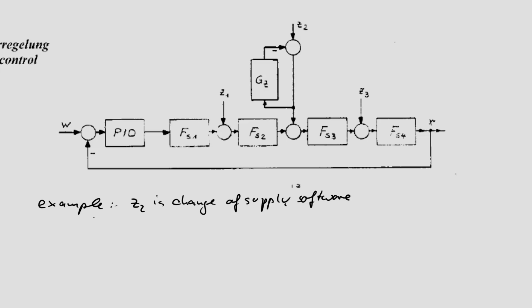And in Germany, we have a voltage of 230 volts plus and minus 10%. So it can be 207, but it can also be 253. So there could be a change of plus or minus 10 to 15%, and this can influence the behavior of the loop.